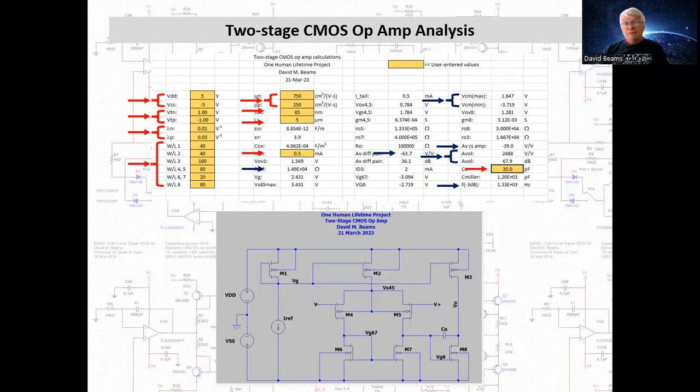Now, there's one difference between this 2-stage op amp and the LTSpice model. In the schematic of the LTSpice device, these 2 transistors in the differential pair have their substrates tied to the positive supply rail. So the body effect will come into play in the calculations of the LTSpice model. Here, to simplify the analysis, the substrates are connected to the sources, so there is no source to substrate voltage difference, and the body effect does not come into play.